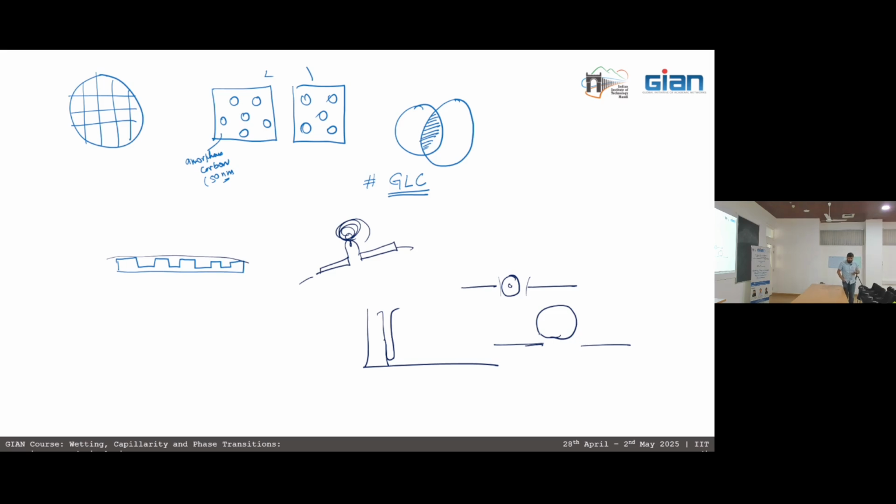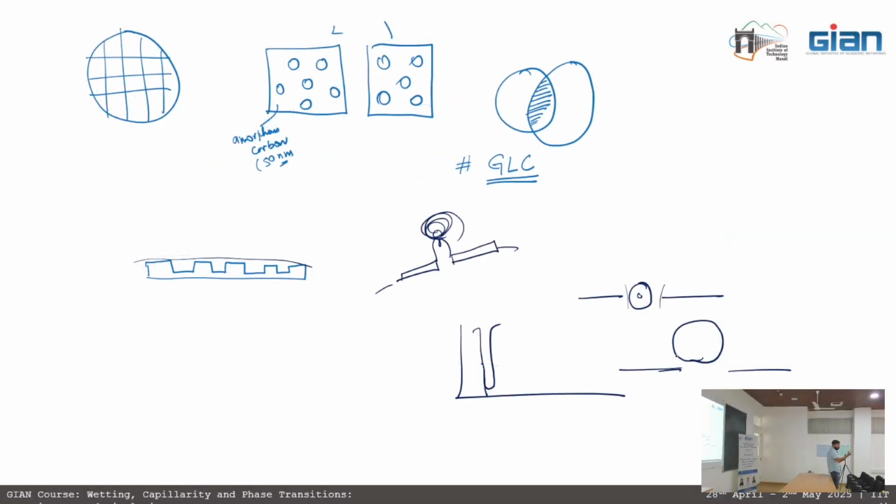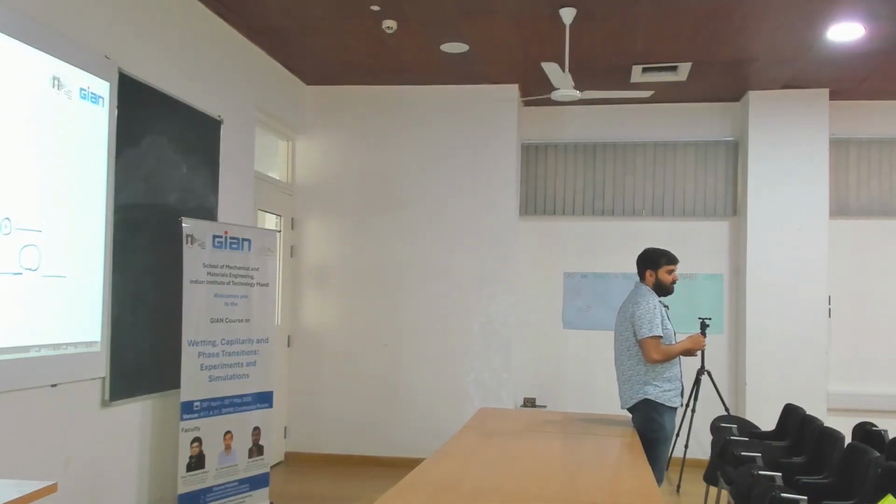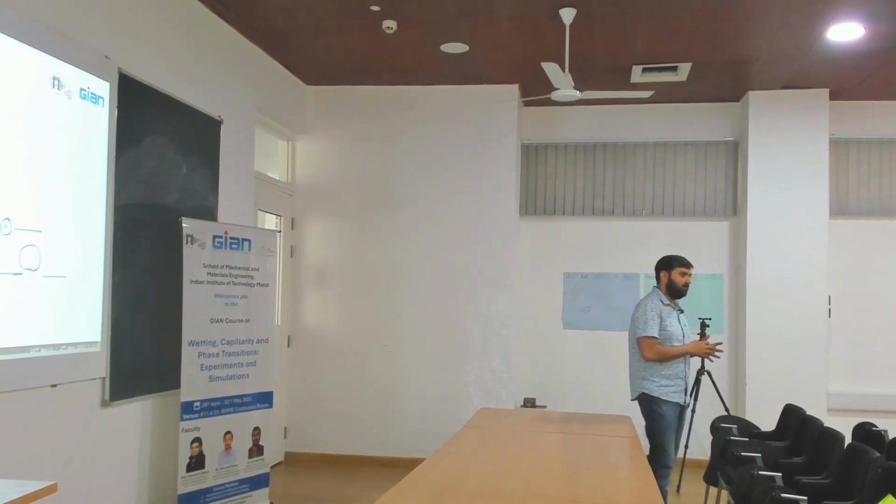The problem in these microchannels is that once the phase change occurs, pinning of the bubbles occurs, and it causes dry out in the microchannels. If we are able to produce homogeneous bubbles in the first place, then the length can be optimized so that we don't have the problem of pinning and dry outs. That was the main idea behind this work, to make a nanobubble emitter.